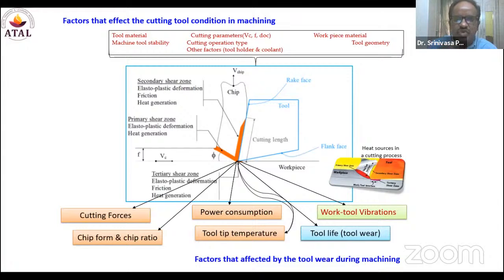It is also going to influence the quality of the machining in the form of surface roughness, which is available on the produced parts. It can be surface roughness or flank wear; both require stoppage of the machinery. Then only are you able to take out the workpiece from the job, or remove the cutting tool from the spindle. Stopping the machinery, and removal of the cutting tool or workpiece, consumes a lot of time. If this process is handled while the machining is in running condition, again it will be an added advantage.